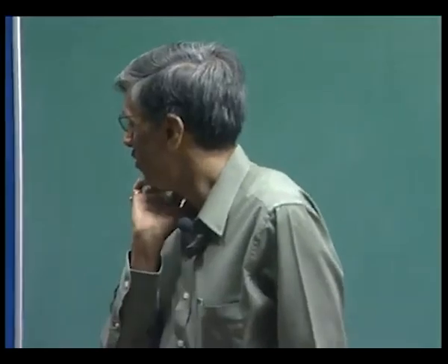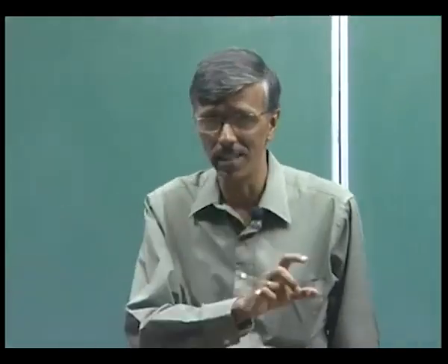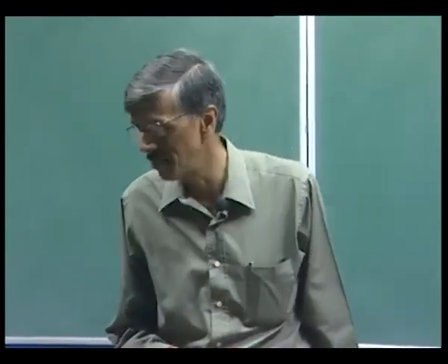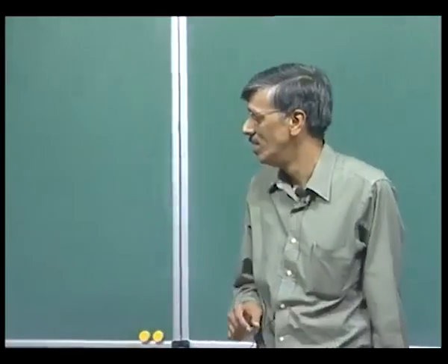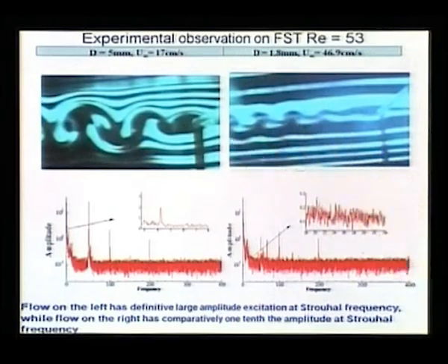So, we are discussing instabilities for bluff body flows, and one of the redeeming features of this particular flow is that here you see temporal instability, quite unlike streamlined bodies we had discussed so far, where we mostly confined ourselves to spatial instabilities. Let me show you one of the figures that we saw in the introductory part of the course, where we showed some experimental results conducted here in one of our tunnels.